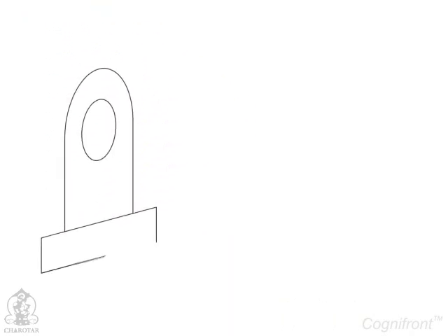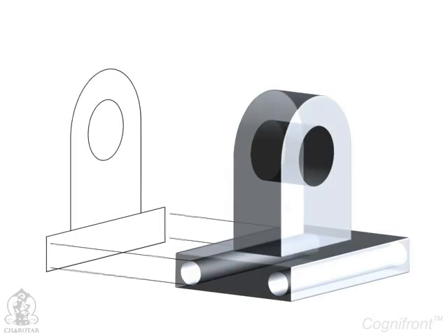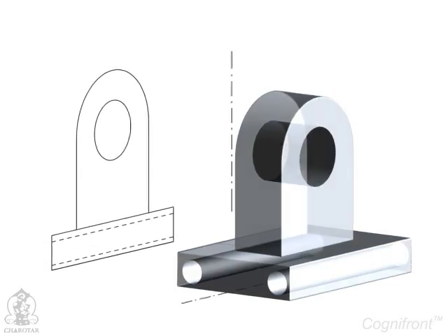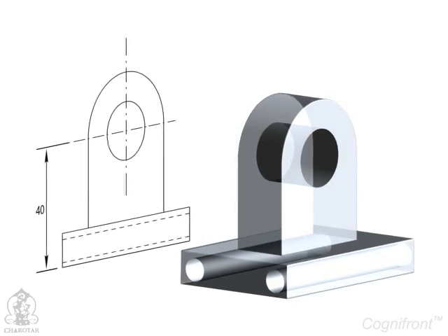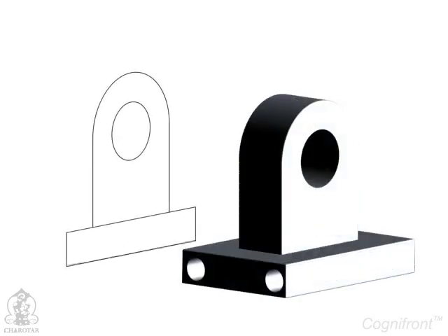Next element is line. Lines are the predominant and the fundamental drawing element in every drawing. Various types of lines are used to represent different entities, like visible lines are used for drawing outlines of visible edges and surface lines which represent the objects. These are drawn in bold, dark and continuous lines.